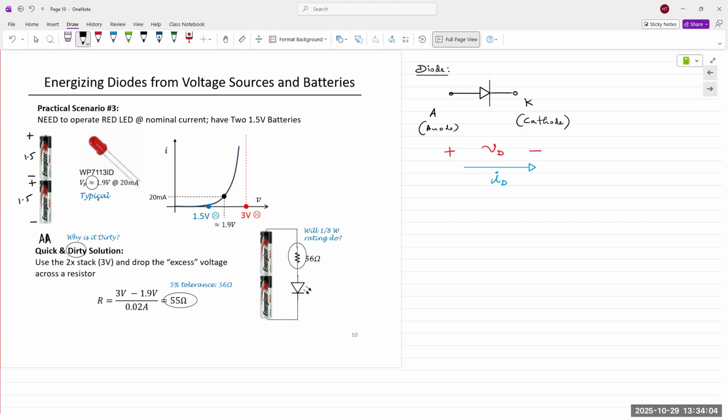But with 3 volts and a battery this large, if you connect it directly to an LED, it's going to turn on very bright, and there's also going to be a large amount of current flowing through. So the LED might burn out very quickly, and we don't want that.